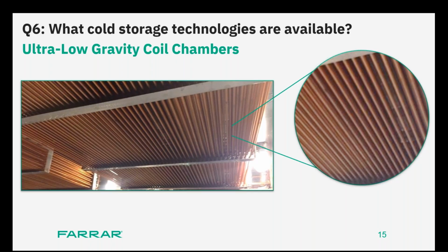So one of the ways to mitigate it, though, is you can put into it compressed dry air. So you have the owners bring us compressed dry air, and that compressed dry air is usually at a minimum minus 40 degrees C dew point. And that way, once that air comes in, it'll pressurize the chamber, and it puts a nice little positive pressure that will eventually go into the minus 20, then to the 5 degrees C vestibule cold room, and then out into your interstitial hallway.